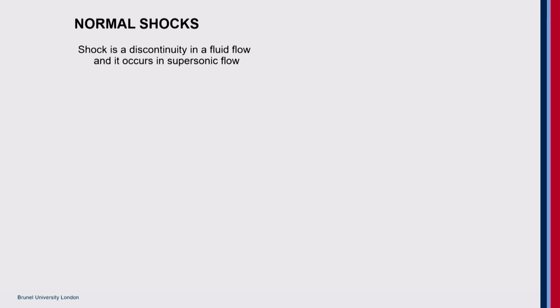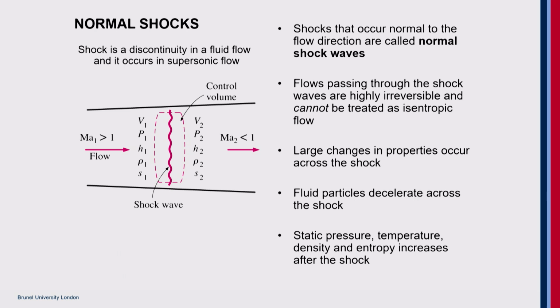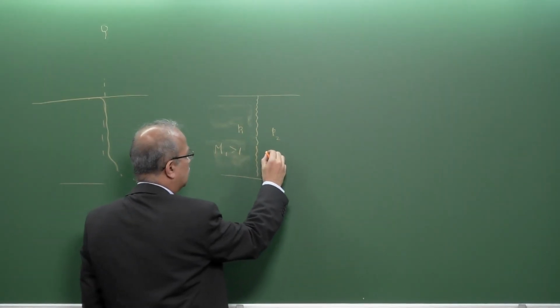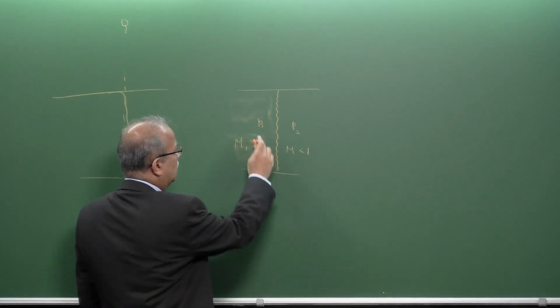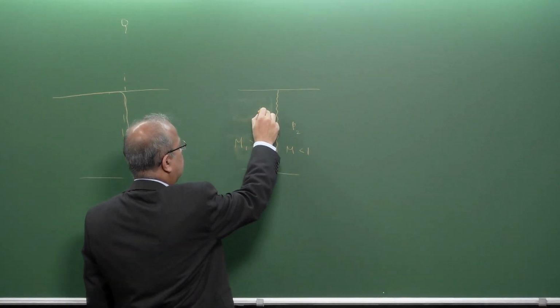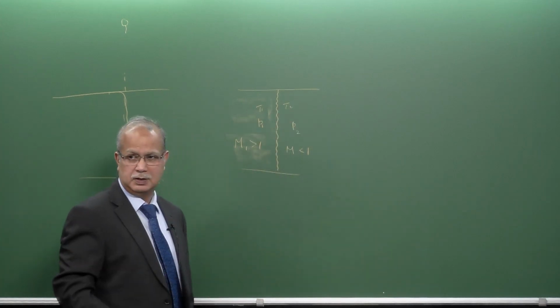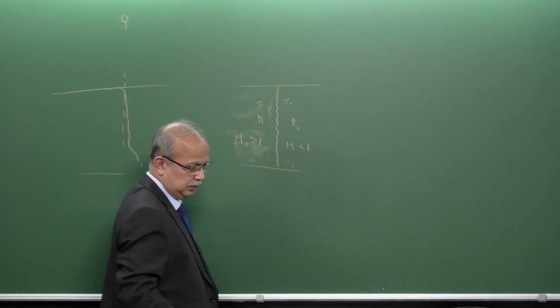It occurs in supersonic conditions. So when a shock wave occurs, all the properties spontaneously jump. One of the things you see here is that when the flow is coming in supersonic, M1 greater than 1, immediately after the shock, the flow becomes subsonic. All the other properties, static pressure and static temperature, increase, but the total pressure decreases. And the entropy, S1, will increase.